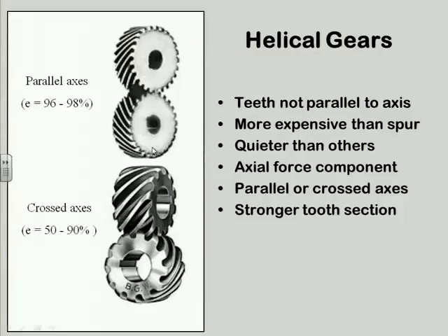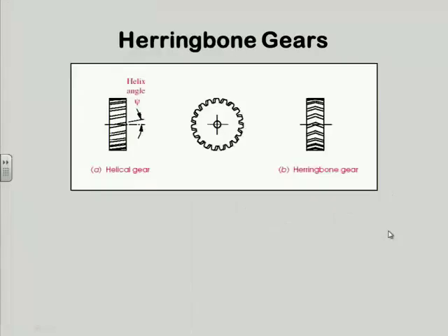So I have a longer hypotenuse on the angle, and there's more meat in the direction of loading, because the loading is now normal to the helix. So I actually pick up a little bit of cross-section for the same size teeth, which of course you trade off by making the thing smaller and lighter and less material and thus less expensive, and get back to the same strength, right? Harder to disengage, as I mentioned.